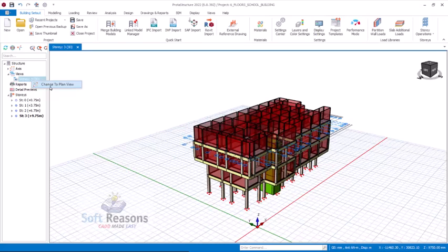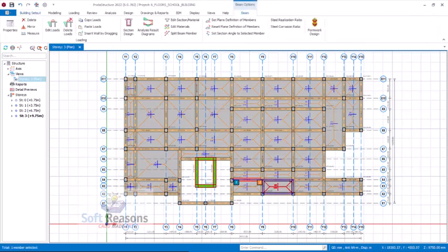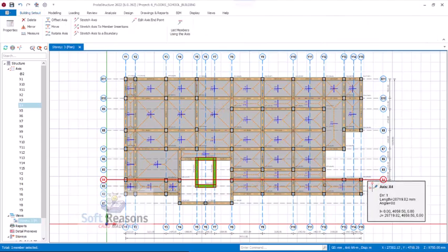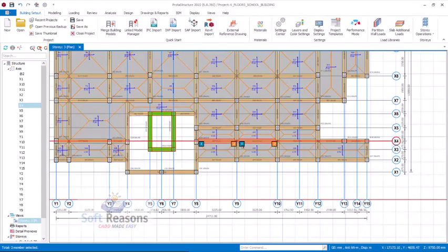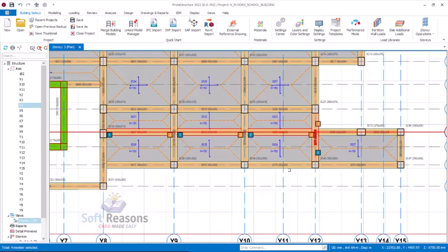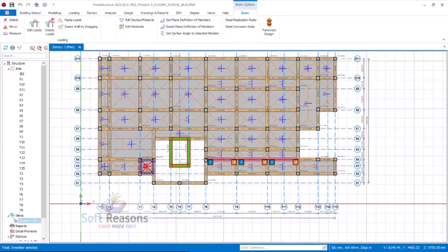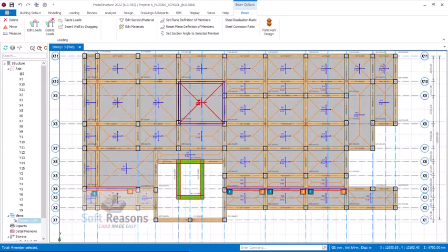We will also have to navigate to the plan view. So on the plan view, it's not all of these beams that will have the load placed on them. So these beams do not bear wall load. Okay, so we select them accordingly, to be able to get what we intended to get successfully.